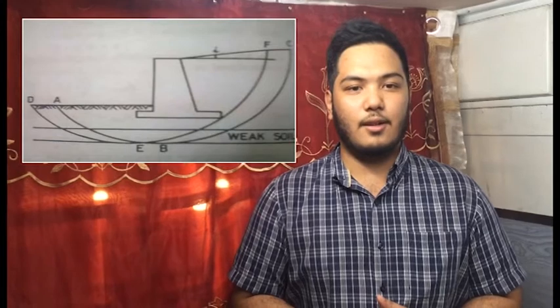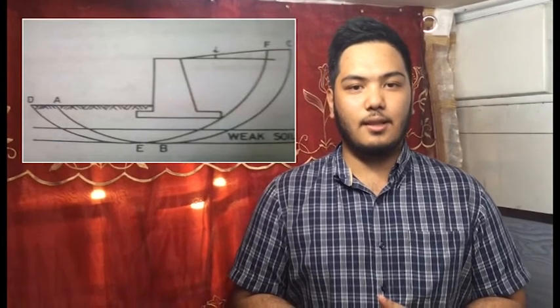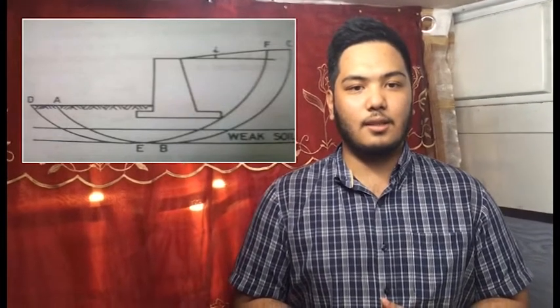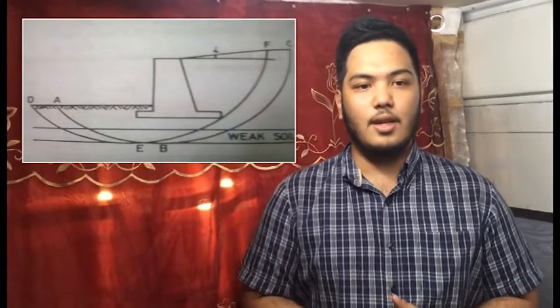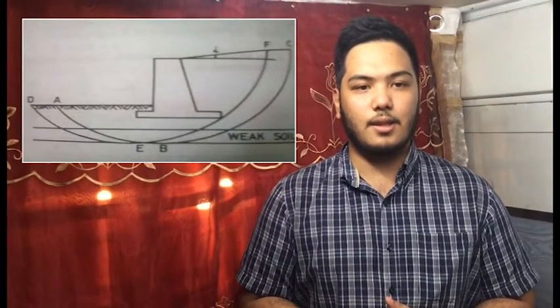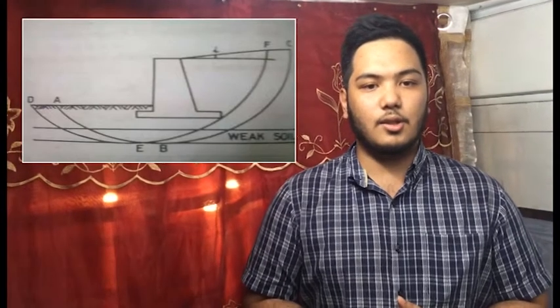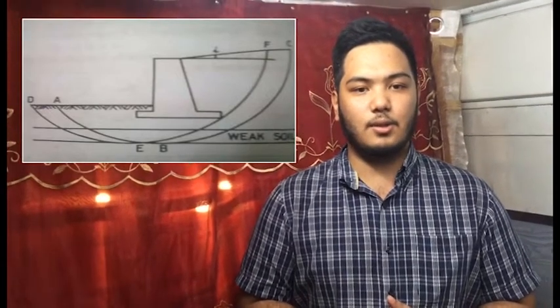For backfills having slope less than 10 degrees, it has been seen that the critical failure surface DEF passes through the edge of the heel slab, as shown in the figure. In this condition, the possibility of excessive settlement should also be checked.